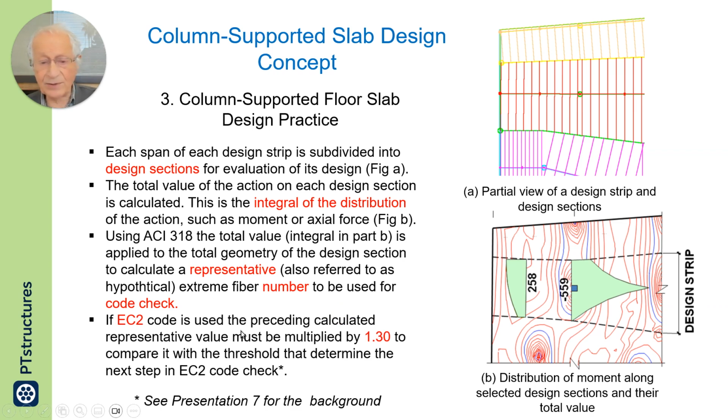If EC2 is used, this preceding calculated value must be multiplied by 1.3 to compare it with the EC2 recommended thresholds for initiation of cracking or otherwise. Now here, presentation 7 explains why this is the case.